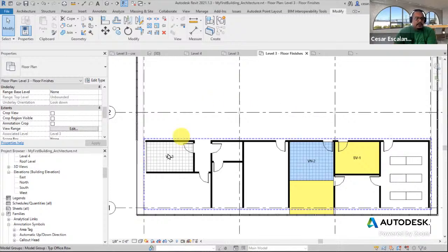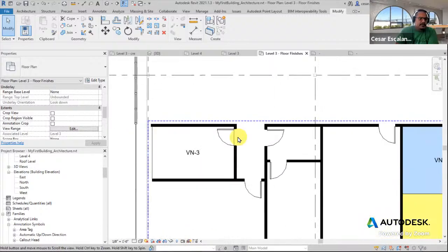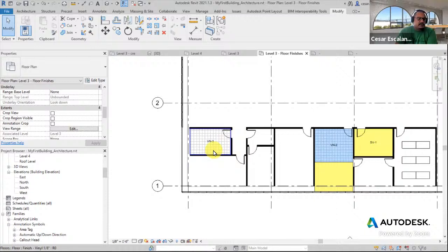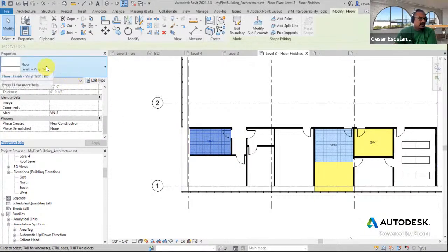If your scope includes 3D renders and 3D views, and you actually want to schedule the plans and have a more granular representation of the finishes, then use method number two, which will create floors on top of a slab.